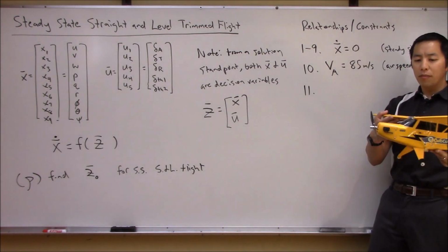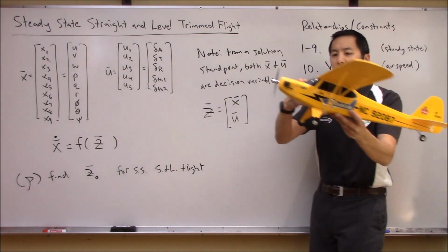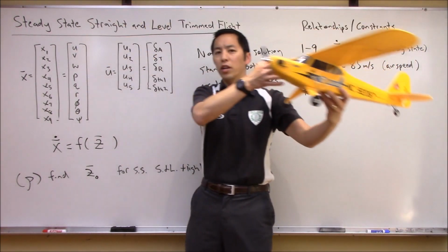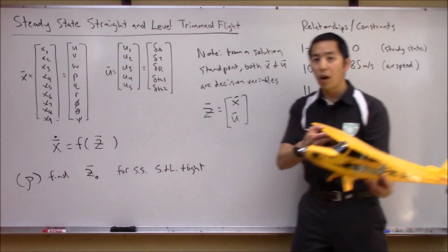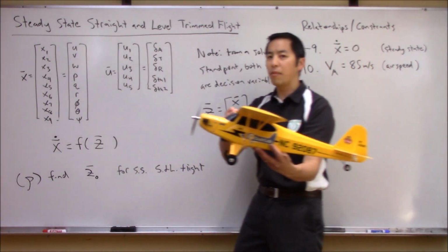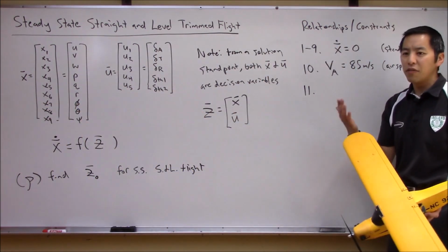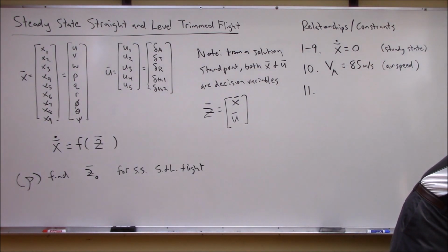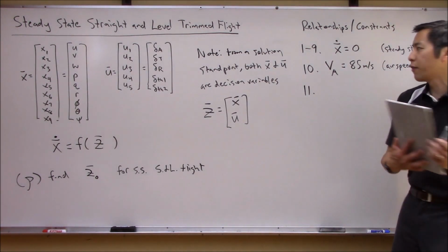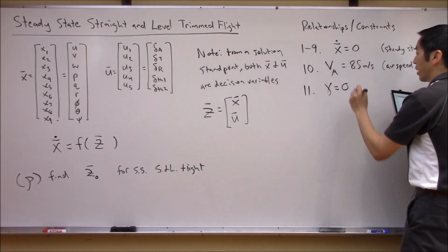Usually what this implies is, again, we want a combination of, I don't want the aircraft to be gaining altitude, and I don't want it to be losing altitude as you go through this maneuver, right? I want it to maintain the same altitude, okay? So there's a couple of ways we can enforce this idea of same altitude. The one that I'm going to propose right now is, let's put a constraint on the flight path angle gamma here. So gamma is equal to 0, okay?